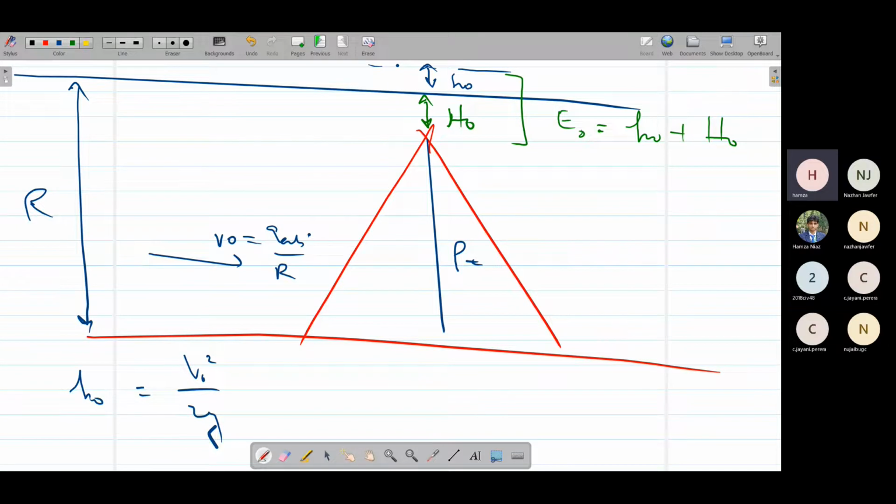Now for the upstream side, we'll calculate its specific energy by a similar method. First, we'll get this normal depth of flow. We'll get this D naught by subtracting the river bed level from the highest flood level. In this normal depth of flow, we'll add some efflux value because there will be some damming action. This value we would assume ourselves because we do not know it.